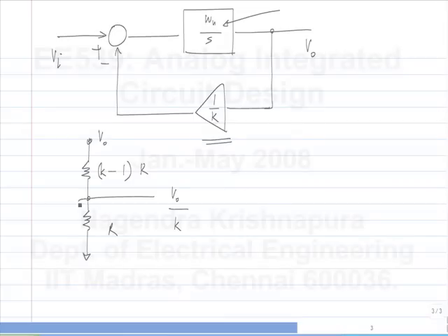If we have a parasitic capacitor here, there will be a pole in the response between the input of the voltage divider and the output of the voltage divider. Okay. So you can have parasitic poles because of the feedback network also, and in reality this does happen. Both the forward path and the feedback path will have parasitic poles. Before, I put all of the parasitics in this, but it's really the parasitic pole in the entire loop gain that matters for the stability of the system. Okay, not really the forward path alone.